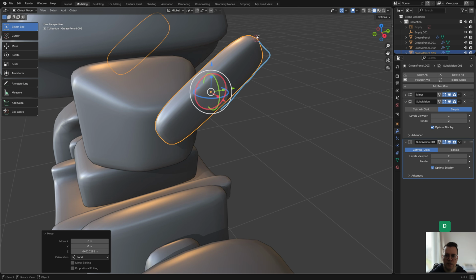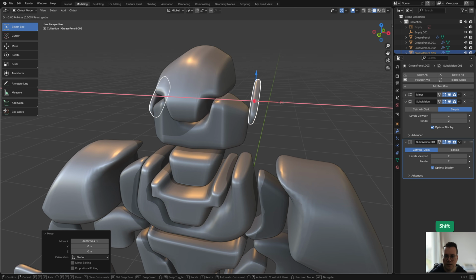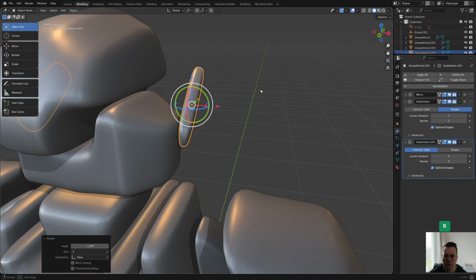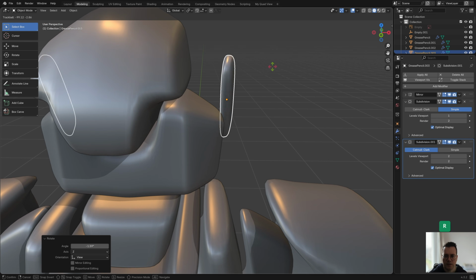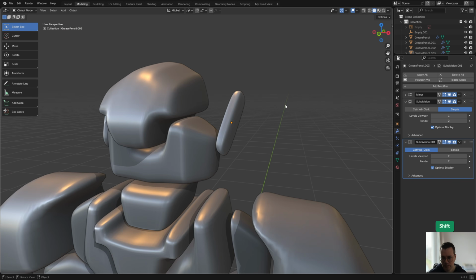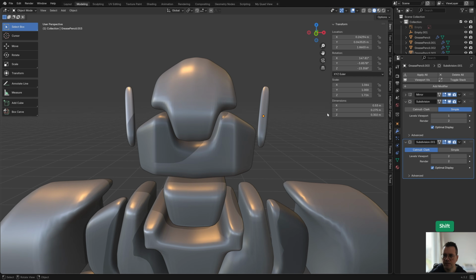And then I can just quickly erase this annotation. And maybe we can move this a bit closer here, so it becomes kind of an antenna or something. And if you just want to be able to freely rotate something, you can just press R twice. Then you can just kind of rotate it like this. And by the way, you can also find those rotation values. If you press N here, then you will get the option panel. And then as you can see here, there's also these rotation values. And I would recommend holding Shift. Otherwise it will go very fast. So with holding Shift, you kind of have a more subtle control over those values. And also the scale and location values are here.